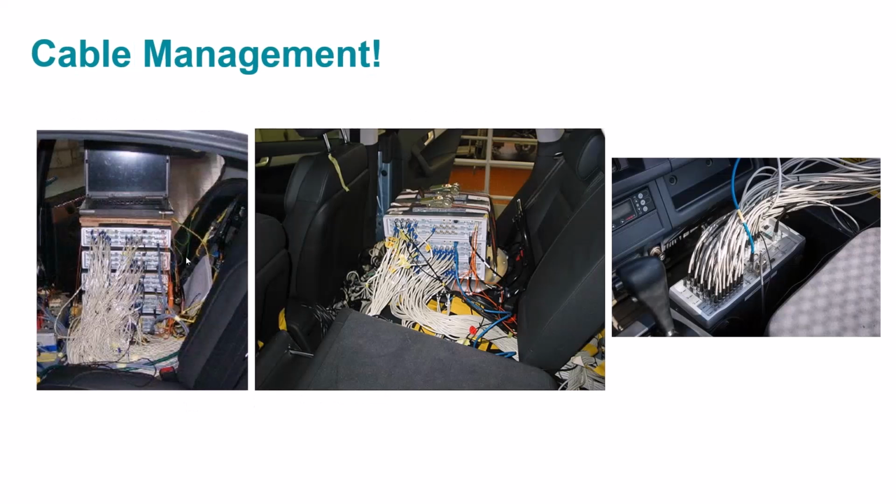Okay, here's that cable management picture. If these were all ICP, but you didn't have something that was able to supply that constant current, you would need that signal conditioner. And for every single cable that you plug into your measurement system, you have to double the cables in the signal conditioner. If you're measuring a lot of channels, that becomes very cumbersome.